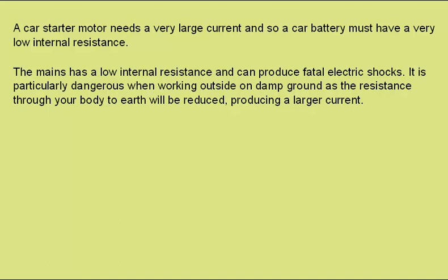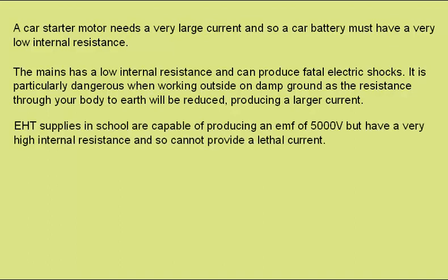It's particularly dangerous when you're working outside on damp ground, as the resistance through your body to earth will be reduced, producing a larger current. Extra high tension supplies, or EHT supplies, in schools are capable of producing an EMF of around 5,000 volts, but they have a very high internal resistance built in to prevent them providing a lethal current.